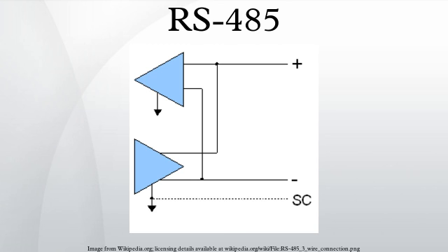By using repeaters and multi-repeaters, very large RS-485 networks can be formed. TSB-89A, the application guidelines for TIA/EIA-485-A, has one diagram called star configuration. Not recommended. Using an RS-485 multi-repeater can allow for star configurations with home-run connections similar to Ethernet hub star implementations. Hub star systems allow for very maintainable systems without violating any of the RS-485 specifications. Repeaters can also be used to extend the distance or number of nodes on a network.